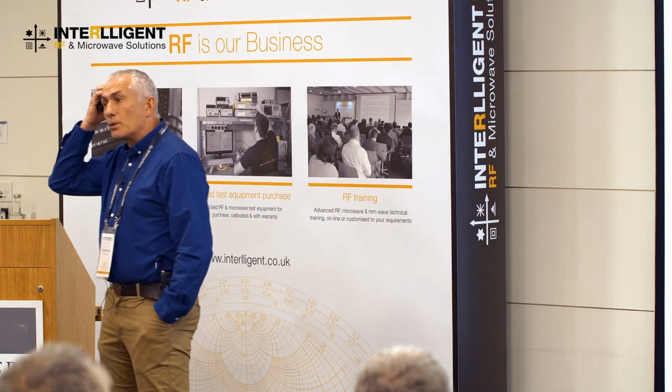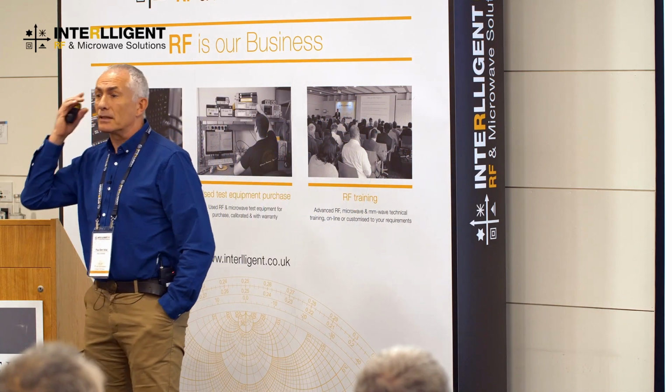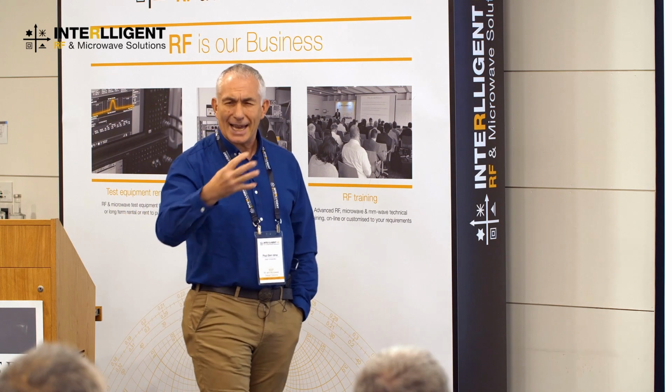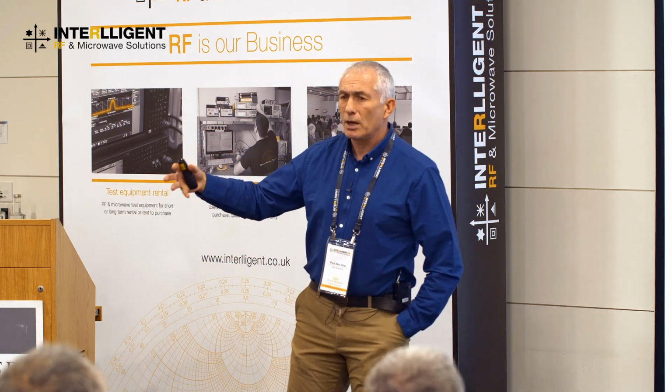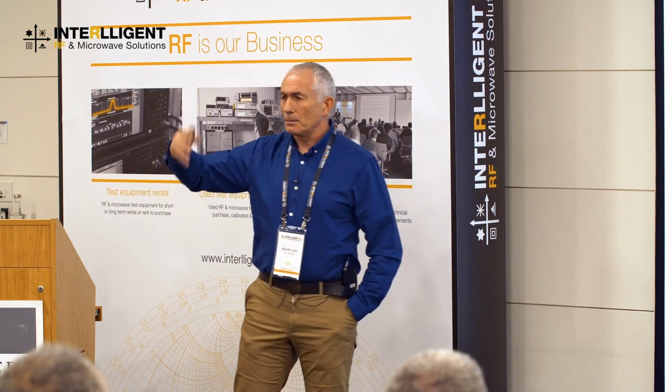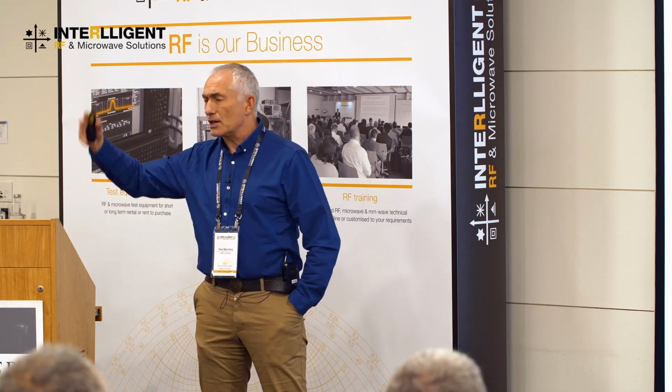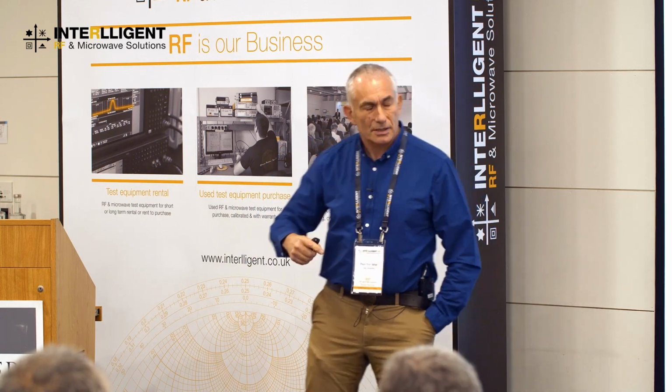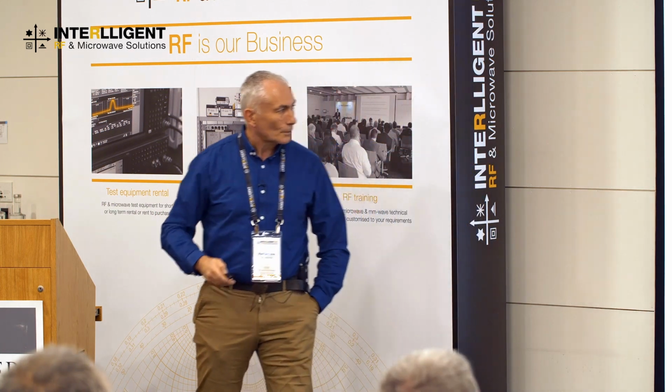You can also use them when you apply very strong electrical fields inside them as well. If you want to do aging experiments, take your polymer, for instance, and pass it through a series of strong electric fields over one day. It is the equivalent of leaving it out in the sun for a couple of years. See if your polymer is going to last. It's a very useful thing to do.